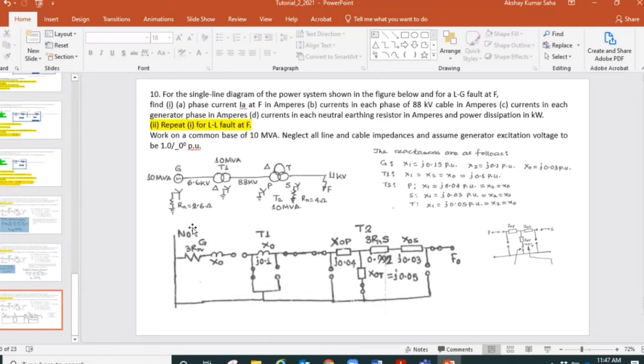We'll consider the value during the calculation time, and then the zero sequence reactance of the generator, and then we put an open here and look at the connection. So we will have to connect it, but one open is missing here because I intentionally dropped the open of the generator because it's not required, it's closed, it's star connected and grounded, so that is closed, that's not shown here.